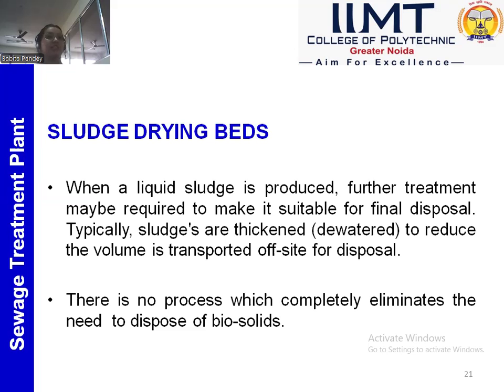Typically, sludge is thickened and dewatered to reduce the volume in transport so that it is easy to transport for site disposal, because sites are very far from the cities and everything. There is no process which completely eliminates the need to deposit the biosolids.